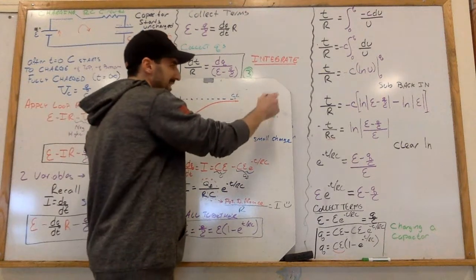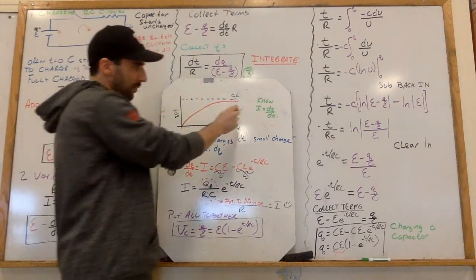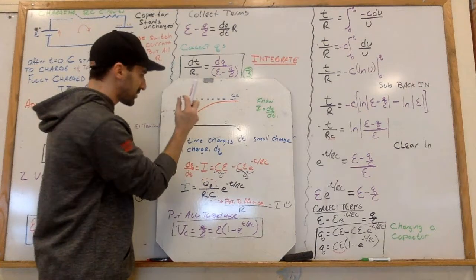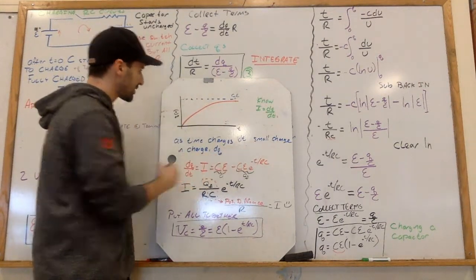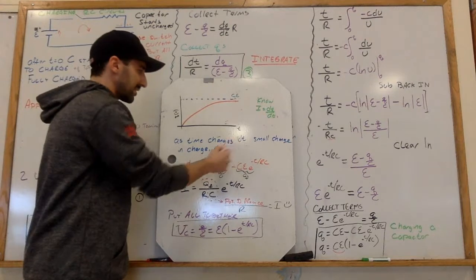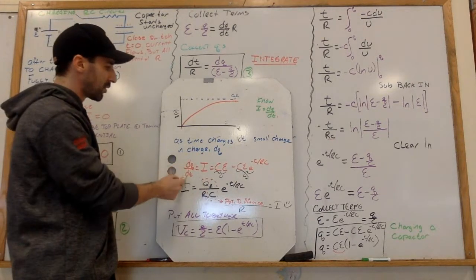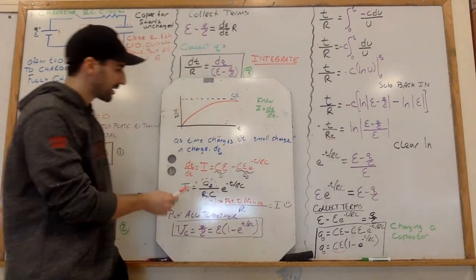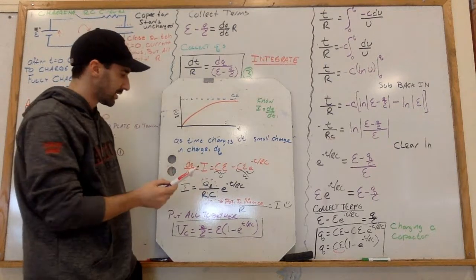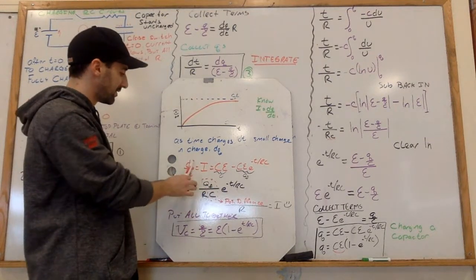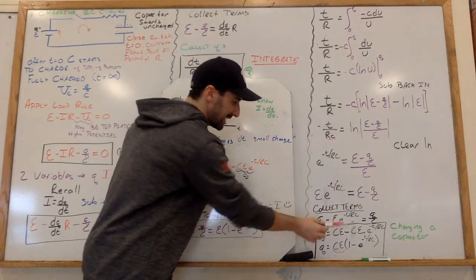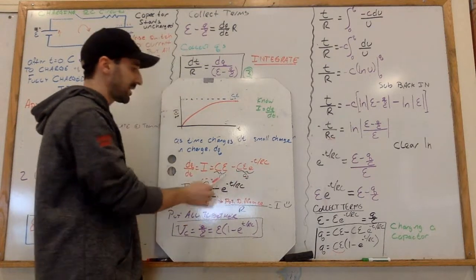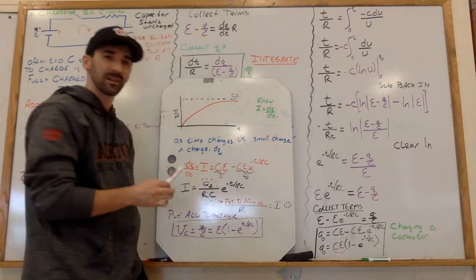So now, if I want to take this one step further, perhaps, I know, again, I is equal to dq over dt. In other words, as time changes by a very small amount dt, there are small changes in my charge. So I know dq over dt is equal to I. I said integrate, I apologize. I'm taking the derivative, dq over dt. The derivative of the constant CE is 0, minus the derivative of CE e to the negative t over RC. This is actually like my final charge.